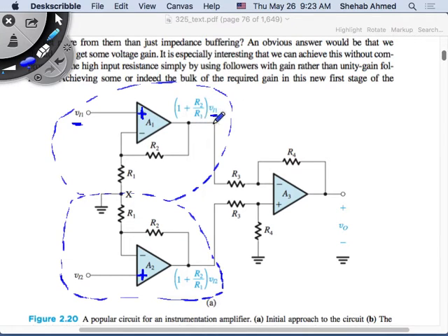So here at this node I will have this voltage, and here at this node I will have this voltage. What if I have a common mode voltage on VI1? Go back to your non-inverting amplifier. What's going to happen? It will pass through, and it will be amplified by the same gain. Right? So which was the main drawback for utilizing the inverting input with signals that have common mode? You cannot deal with it. The common mode will pass through and it will be amplified. Right? So that was a problem there, and it's still a problem here.